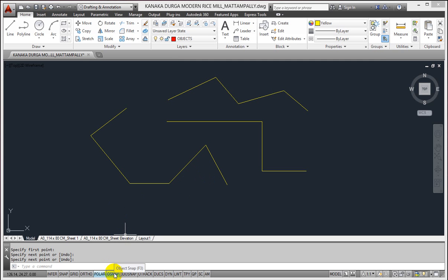The next drawing aid tool is 3D OSnap. This tool controls running object snap for 3D objects. Now we are not going into 3D drawing at present. The 3D object snap can also be toggled on or off by using the F4 key on the keyboard.